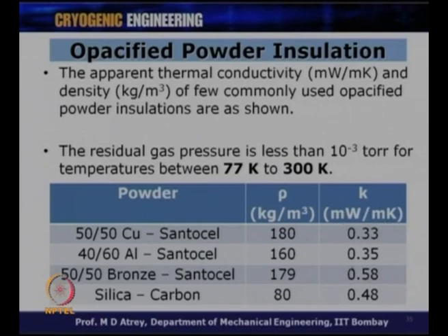So, we could show from here that by having these opacifiers in the evacuated powder, the apparent thermal conductivity has decreased by almost 5 times, and therefore opacifiers are preferred. But then we have conditions like not having vibrations, having it evenly distributed, and things like that.